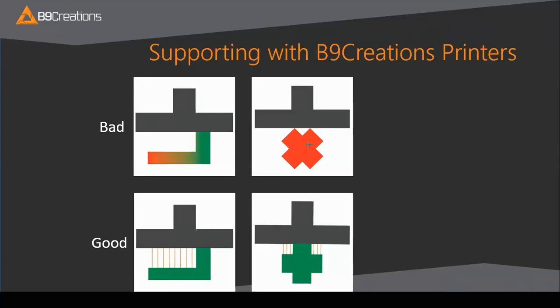The third graphic shows how orientation can affect printability. The first model here that is angled and the tips are only touching the build table would print because the 45-degree angle allows the next layers to build off of the previous layers. However, due to the small points of contact onto the build table, this model is bound to fall off mid-print. If oriented flush with the build table, like in the second model here, it will require supports shown in the graphic and will print.